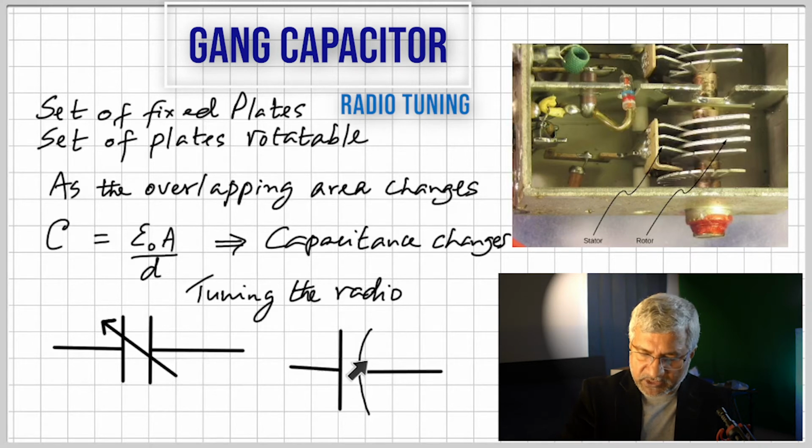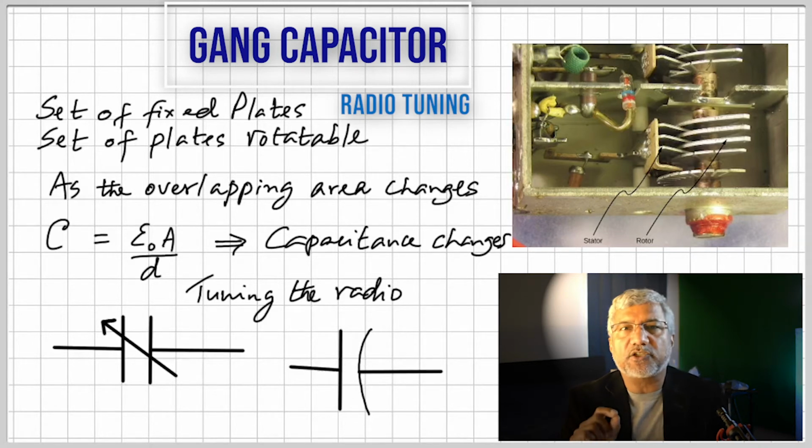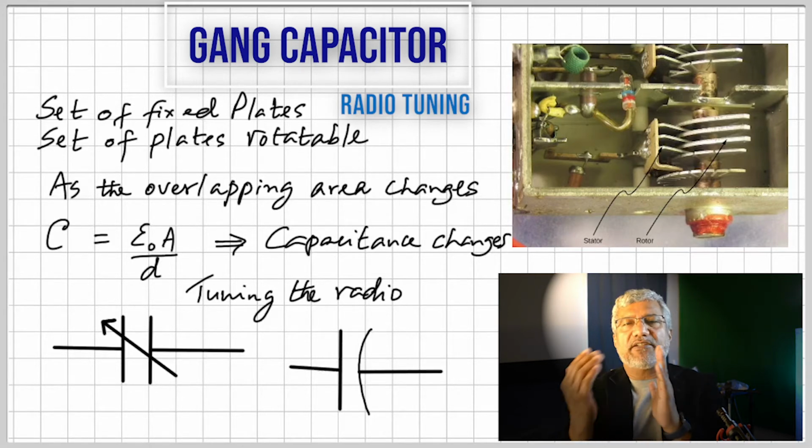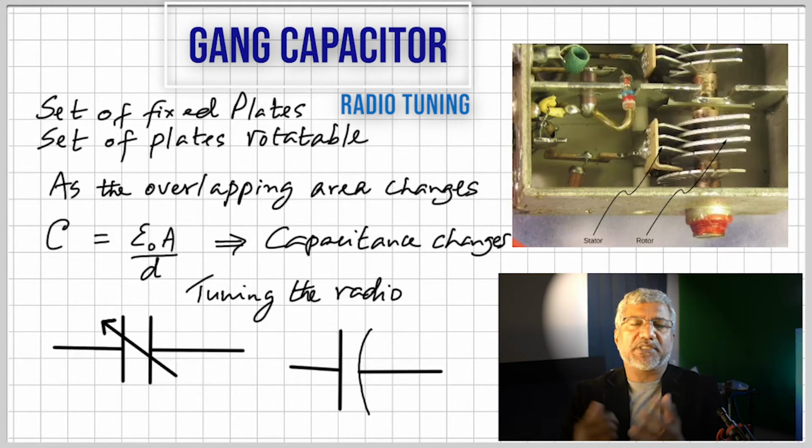And if you see this, that means it's an electrolytic capacitor. Now, what's the difference? For normal capacitors, there is no polarity attached. So when you connect it into a circuit, you can connect either end to the positive or to the negative for standard capacitors.